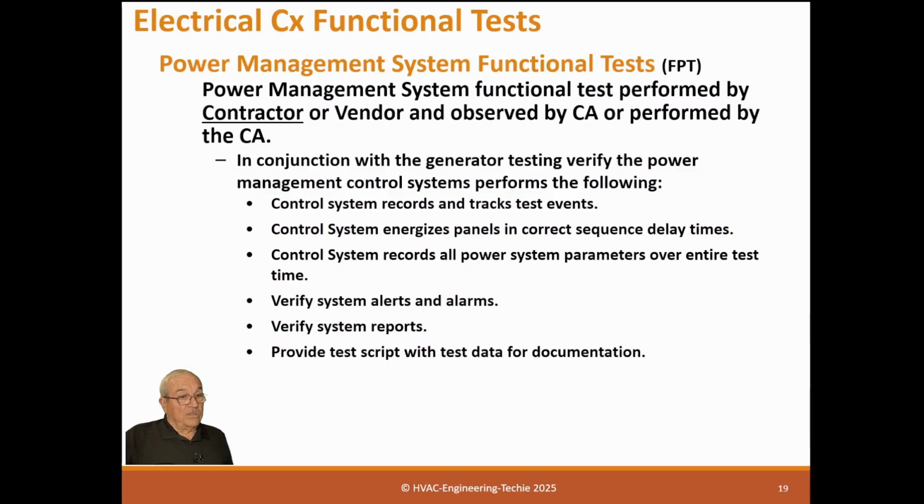Then once the regular power comes back to life, you have to do that over again. Once power comes in and the ATS switches back to normal power, you need to sequence those breakers again so you don't brown out utility power.